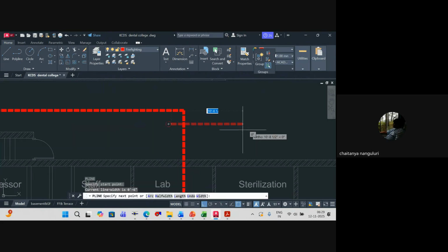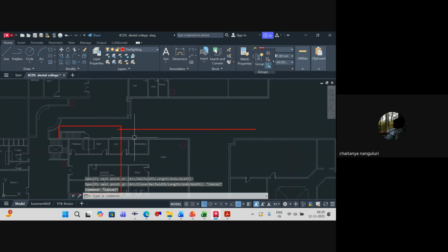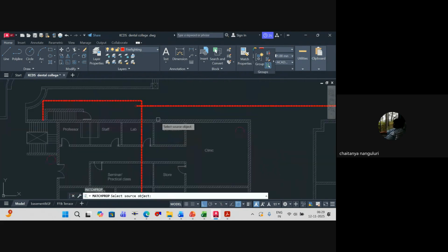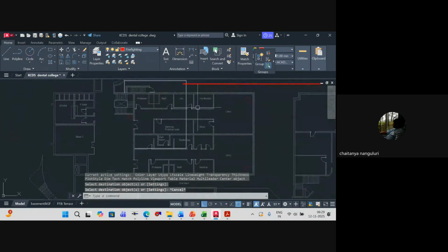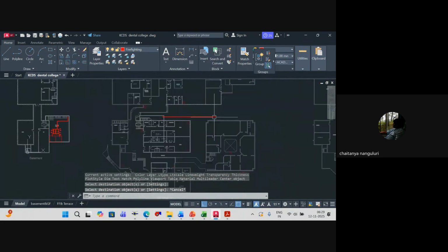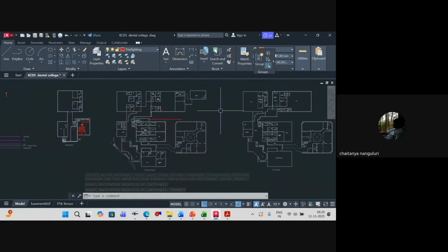From here, the pipe is going to run around the building. I mean, this is the demarcation of the building. That's it, nothing else. Demarcation of the pump room. So from here, the pipe will come out and then it will be connected to your ring main. And then we will connect it to multiple yard hydrants and then to the internal hydrant system as well, to your sprinkler system as well. Understood?